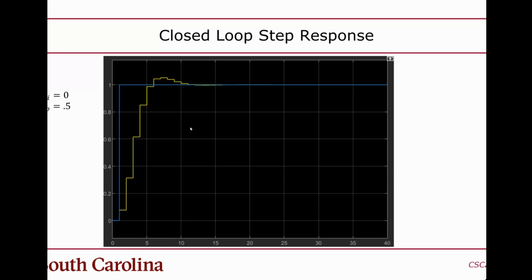And the reason I'm going to talk about real-time scheduling is because obviously, if I'm doing a controller in a processor, I need to be able to issue these control commands at a fixed interval, and I can't miss any deadlines. I need to be able to guarantee that I can achieve the sample rate that I've promised, or that I was targeting in the design of the control system. And so it turns out that real-time guarantees and real-time scheduling can be challenging for a variety of reasons. So I'll get into that in the next lecture.